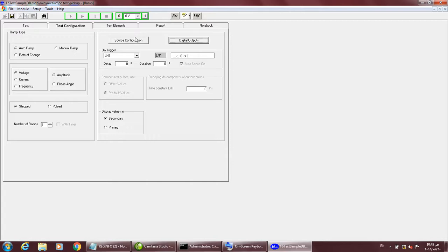Okay. This is logic input. By default in all tests we select LN1. Similarly, for logic input you will use either 1 or 2, not more than that, because our relay has limited contacts. Otherwise we have to connect different outputs to different logic inputs. So we use only one logic output from the relay, any trip contact, and give it as feedback to the